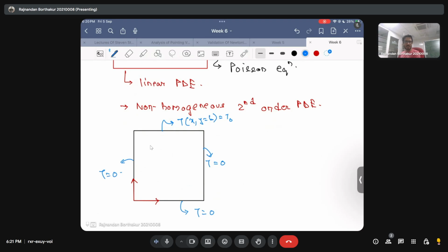And this is a classical scenario where you can apply it in order to evaluate the temperature profile, because you know that your temperature profile will in general be a function of x and y, because it will have variations along x and it will have variations along y. So in general, your T will be a function of x and y. So basically, in order to solve for a temperature field inside this rectangular slab, you need to solve, in this case, the Laplacian equation.